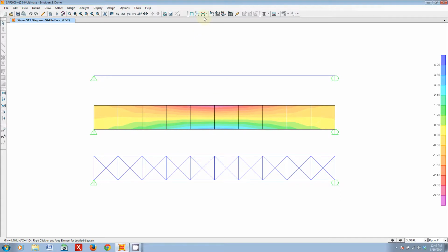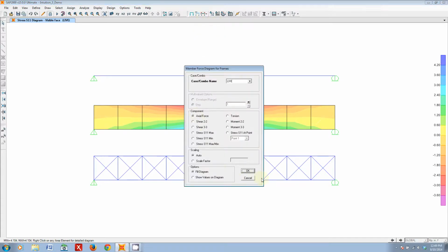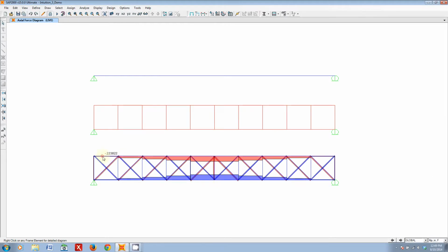What does this look like with our truss? Well, let's check it out. We can use a similar heuristic to how we said that the shear in a beam is carried by the tendons. In this case, the moment in a beam is equivalently carried by the top and bottom chords of a truss. Alright, so what does that mean? Like we saw in our stress distribution on our shell elements, in the top extreme fiber of the beam, we went from 0 stress to a maximum compressive stress.